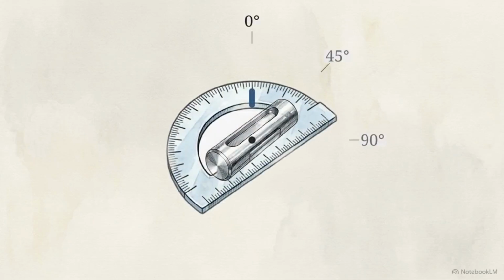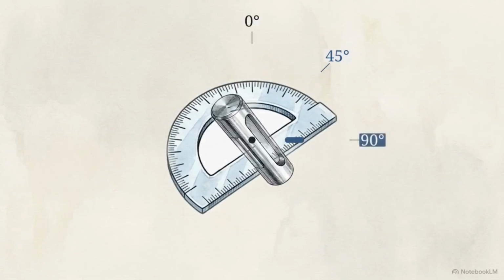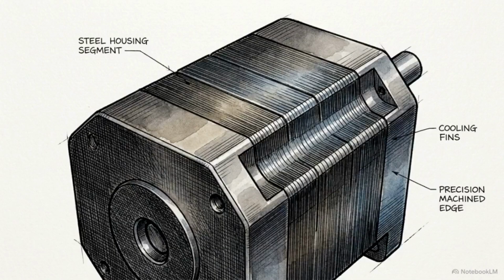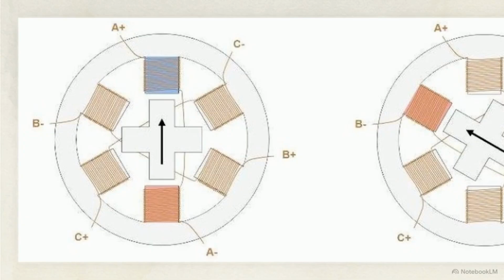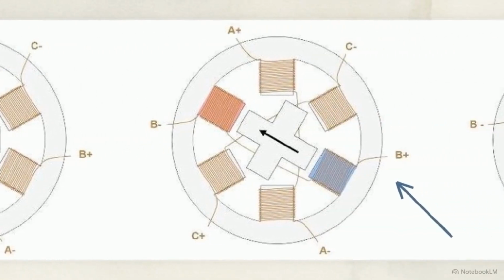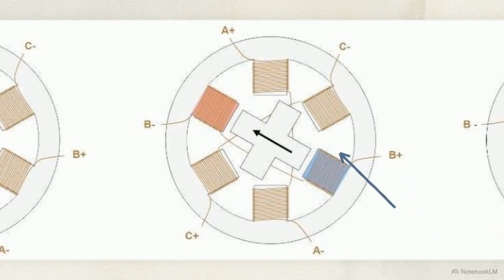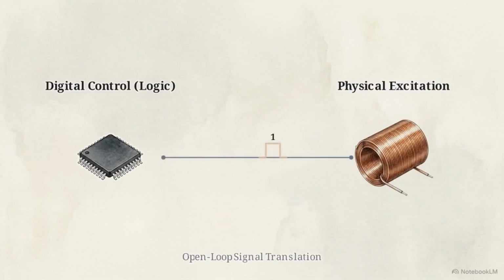However, translating rotation into linear force only works if the system can perfectly control the exact angle of the motor's initial rotation. This requirement introduces the stepper motor, an architecture that purposefully sacrifices smooth, continuous motion to divide a rotation into distinct, measurable physical steps. This diagram shows the internal electromagnetic mechanism. The system fires stator coils in sequence to pull the central rotor into alignment. By shifting the field phase from A coils to B coils, the magnetic field rotates, dragging the rotor exactly one step clockwise. This physical sequence of coil excitation connects directly to the digital ones and zeros produced by a microcontroller.